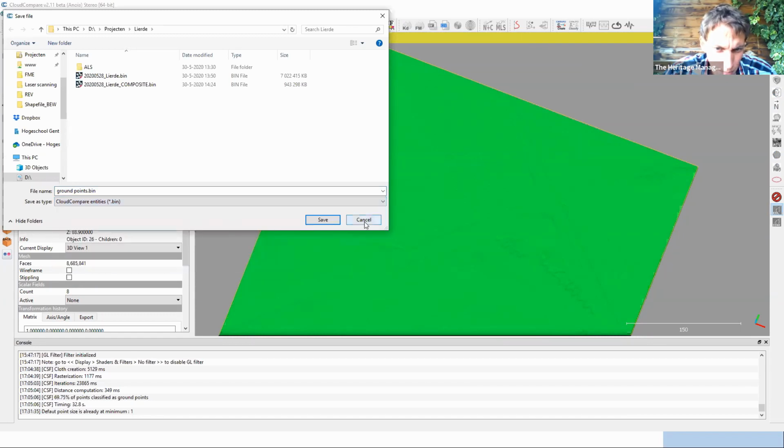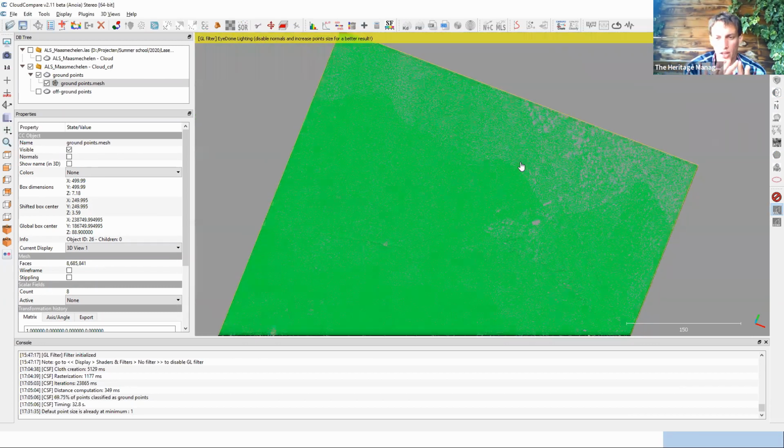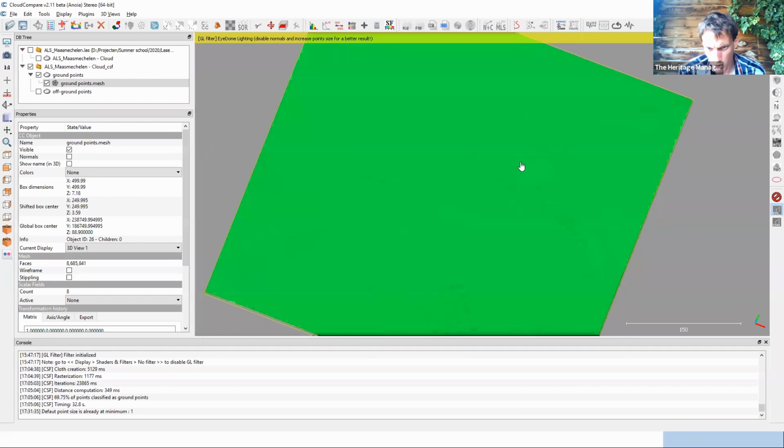One way of using this technique is that when I was working on the Mercator globe that I also demonstrated to you in the previous module, I had a globe with a very complex geometry according to Agisoft. What I did, I extracted these points, I put it in Cloud Compare, and I fitted a sphere on these points. Then I took the sphere from Cloud Compare, I imported it in Agisoft, and I actually had a very simple geometrical representation. So for data reduction, this can be quite useful.